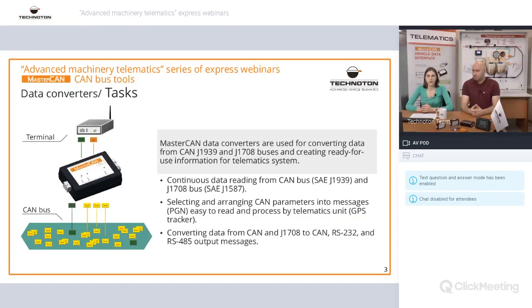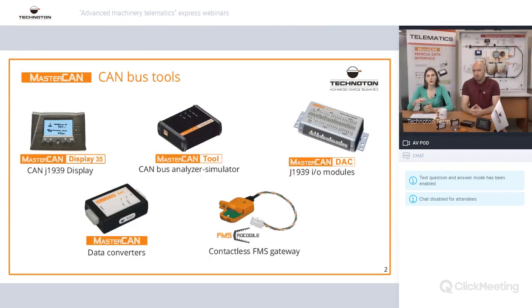So it's important we don't interfere into CAN bus. We just listen to the signal around wires of CAN bus and transmit those parameters to the GPS tracker. Besides these advantages as safe connection, we also have intelligent combination of several CAN buses, like I said, both buses, for example, on Volvo or John Deere trucks.